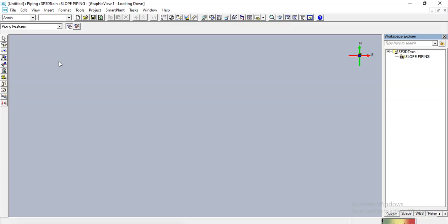Slope line is very important in piping modeling because a normal line we can model normally, but for a slope line we need to give some percentage. So please learn from this video.